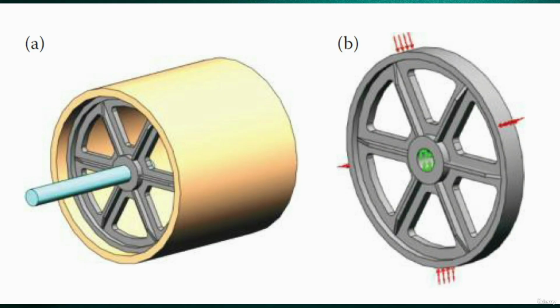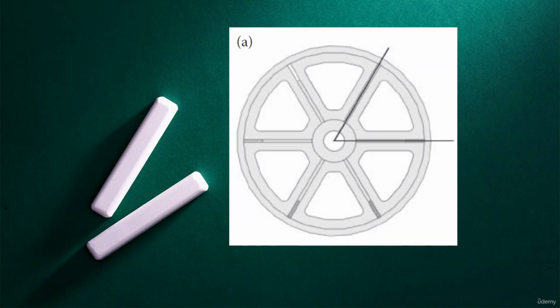In our example, we will analyze the wheel with circular symmetry. If we analyze the entire model, this will require using much more computer resources and time, considering similar boundary conditions and mesh density. So always, when you have an object with circular symmetry, it is recommended to try to reduce the model. In our case, it is enough to analyze only one of the 6 segments of the model. So first, we have to identify that segment.